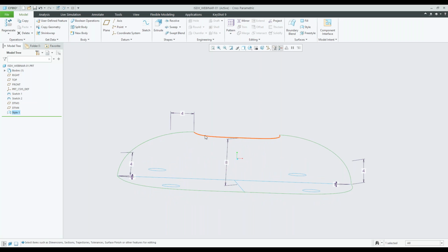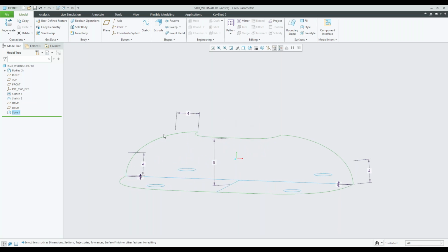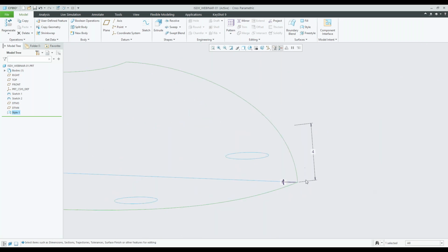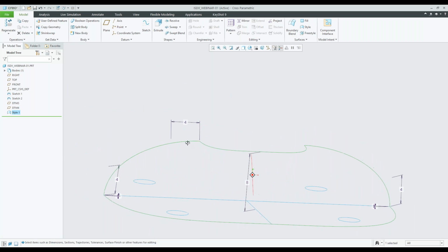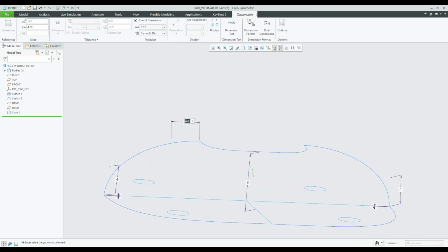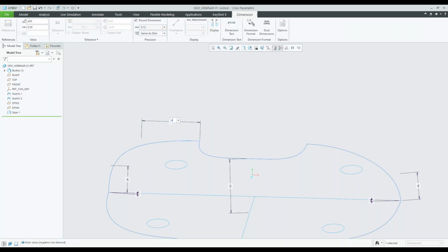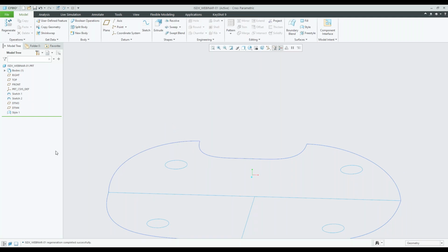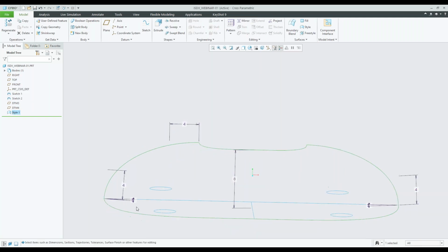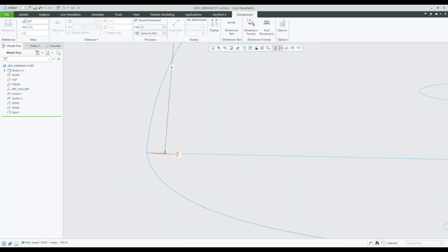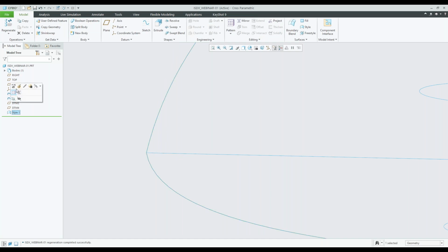you can see those dimensions for the offset for this second curve that we created, the tangency handle length, the draft angle, right? We can change these now. So if I want to change this tangency handle length from 4 to 8, I can do that. There it is. I can change that back to 4. All right, and I can also change that draft dimension from 3. Let's use 12. There it is, and we'll change that back.